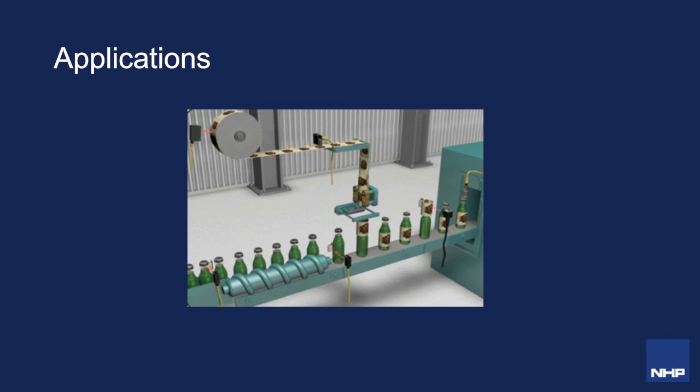orientation. The fourth point, we can see detection if the bottle is filled with liquid, and it also controls the timing of the label application. So the first sensor detected for overfill, but what if the bottle somehow missed the fill process? Now here this is done with a retroreflective sensor. Now this determines there is liquid present. If it was placed higher, it could determine that there's a minimum level that's been detected.